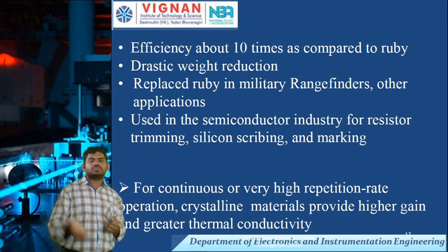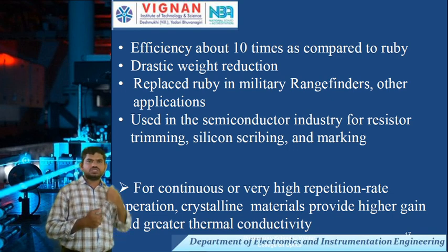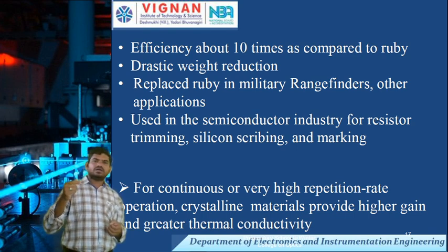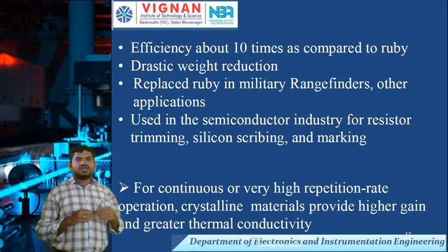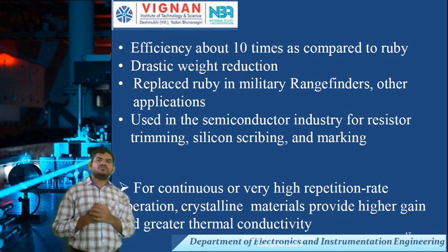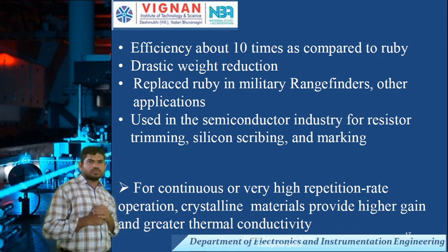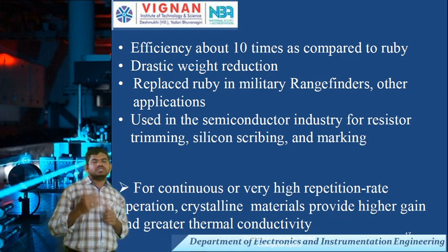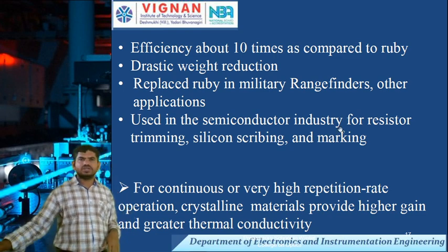That means we are also using it for biomedical applications. It is used in the semiconductor industry for laser trimming, silicon scribing and marking, and for drilling purposes. For continuous or very high repetition rate operation, crystalline material provides higher gain and greater thermal conductivity. Okay, this is the main introduction to the Nd:YAG laser.